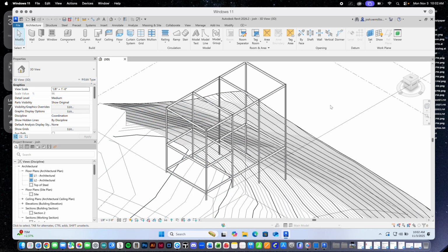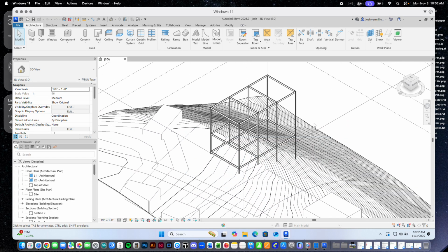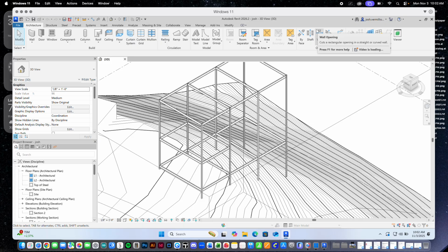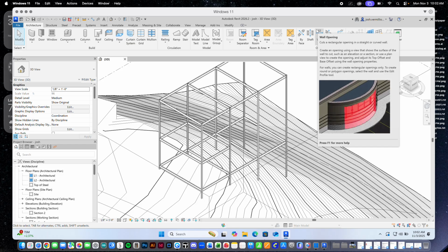Right, so this is where we left off while you guys are getting prepped. Like I said, we have basically the main structural grid in here. We put in columns. First of all, we fine-tuned our grids and levels, so we were able to add columns and beams, thinking about the beams and their clearance along with the floor thickness that we're going to place on top of them. Now we're going to start adding more beams.